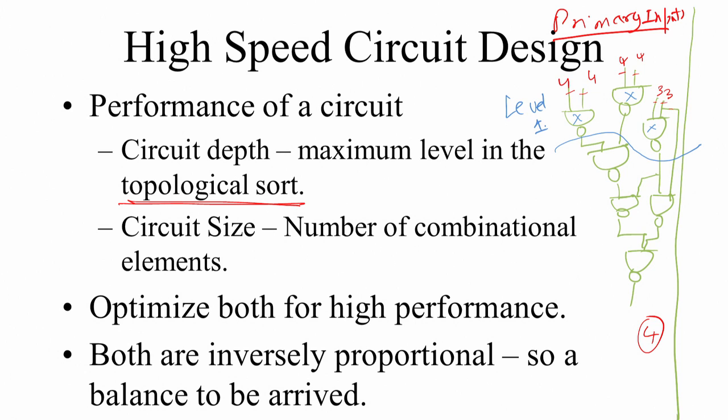Okay. Now, we remove all the level 1 gates and find out what are all the gates that are now inputless. If I remove these 3 gates in level 1, note that these 2 gates actually become inputless. If I remove off these 3 gates, now these brown gates become inputless. So, those are the level 2 gates.